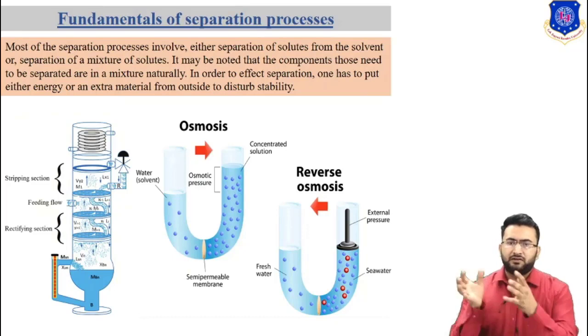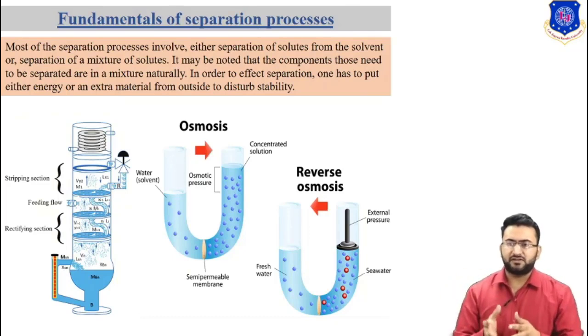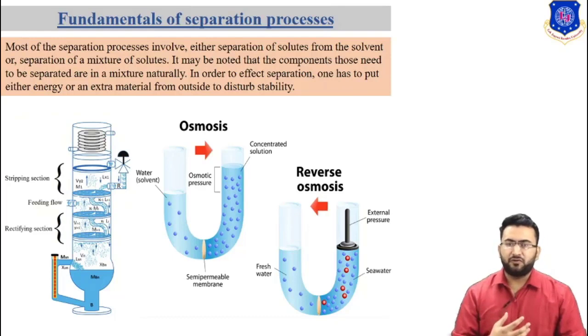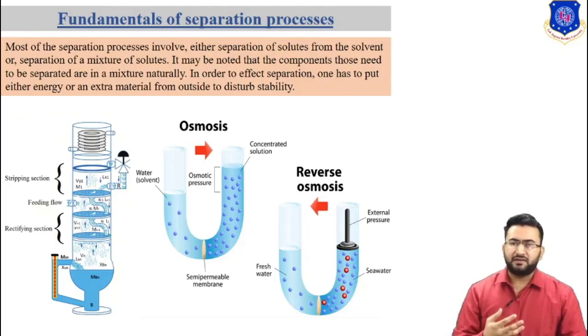Let's consider another case of separation, such as charged colloidal particles which are stable in solution. In such a system, a coagulant like potassium alum, ferric chloride, or calcium oxide, with selection depending upon the operating pH, is added. These coagulants are generally of opposite charge to the colloid. The colloids attach themselves to the coagulant by electrostatic attractive force, and the whole assembly becomes heavier and settles down. In this case, we add an external agent such as a coagulant.